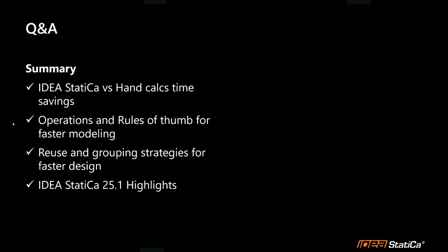I can answer that one. So yeah, for connections with cast in place anchors or adhesive anchors, when we're connecting between steel and concrete, IDEA StatiCa can solve those. Most of that is done within the steel connection software that we looked at today. But if you're looking at an adhesive solution, then we have a separate module called Detail that we use. So we can combine those in one process and analyze that all together to understand what's happening with an adhesive anchor.